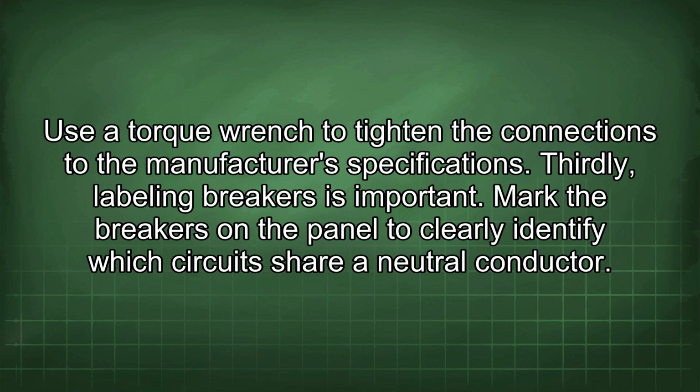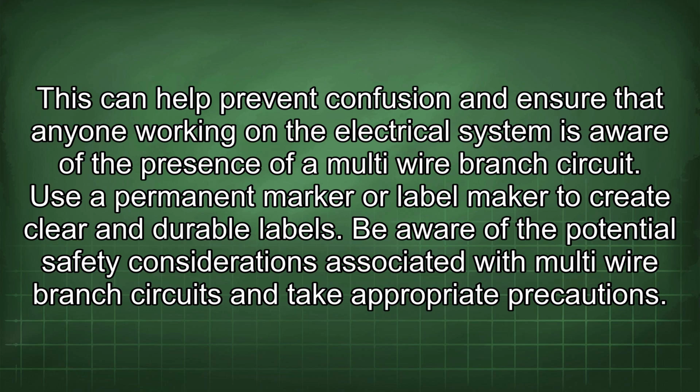Thirdly, labeling breakers is important. Mark the breakers on the panel to clearly identify which circuits share a neutral conductor. This can help prevent confusion and ensure that anyone working on the electrical system is aware of the presence of a multi-wire branch circuit. Use a permanent marker or label maker to create clear and durable labels.